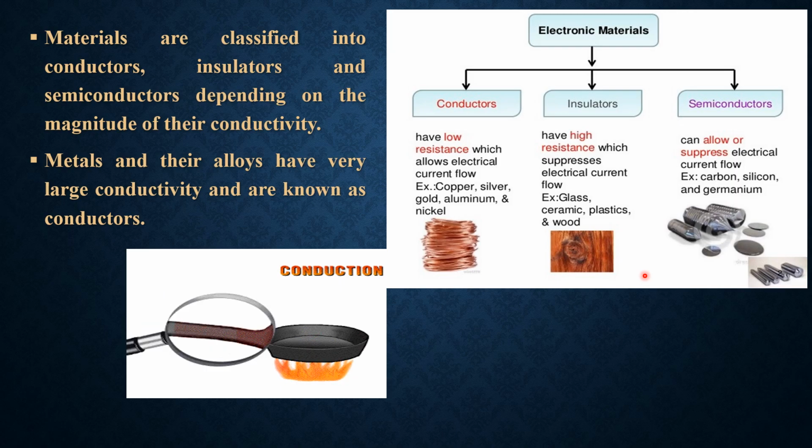Some specific insulating materials are used for storing electrical energy and are called dielectric materials, such as mica, ceramic, paper, etc. These materials are used as dielectrics in capacitors. The number of valence electrons is more than 4, and the energy gap between valence and conduction band is very large. Examples of insulators are mica, rubber, ceramic, glass, diamond, wood, plastic, etc.